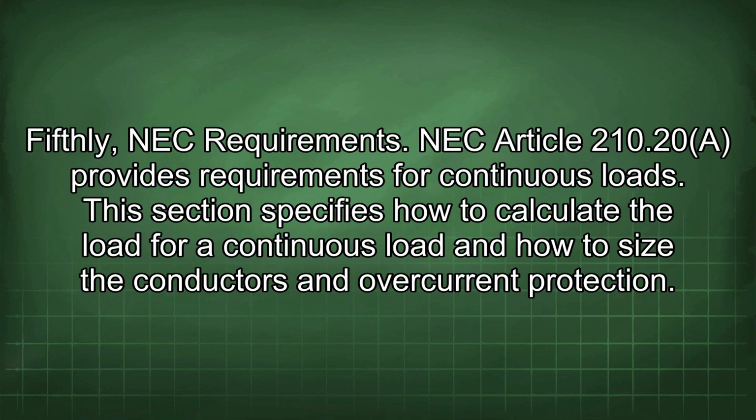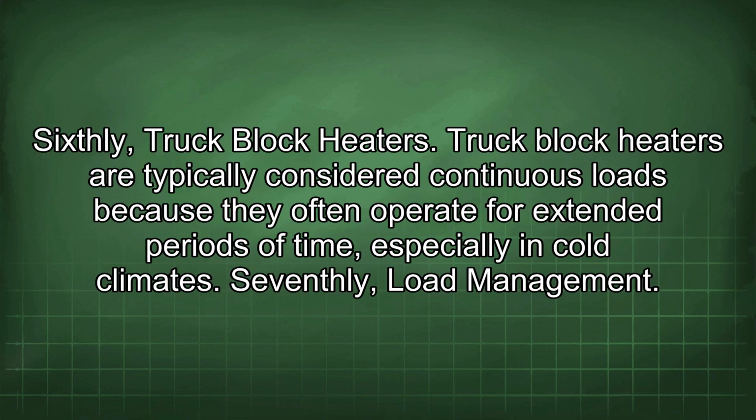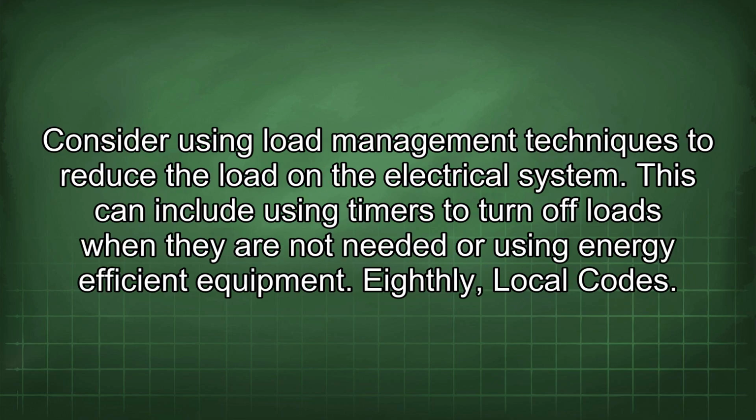Fifthly, NEC requirements. NEC Article 210.20 provides requirements for continuous loads. This section specifies how to calculate the load for a continuous load and how to size the conductors and overcurrent protection. Sixthly, truck block heaters. Truck block heaters are typically considered continuous loads because they often operate for extended periods of time, especially in cold climates. Seventhly, load management. Consider using load management techniques to reduce the load on the electrical system.